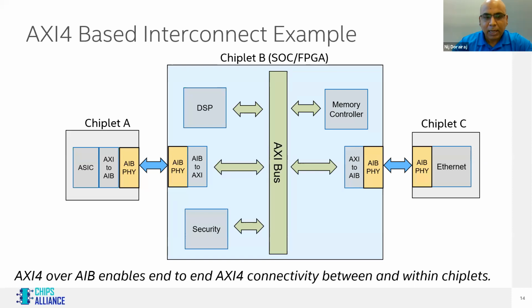So you can see that by providing this AXI layer, we have enabled end-to-end AXI connectivity, and this will ease chip development because I'm able to bring standard AXI components onto the SoC and talk to my chiplet over a standard protocol.